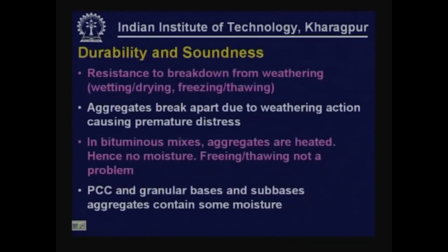Durability or soundness is the resistance to breakdown of the aggregates from weathering, which is the wetting and drying process, and also freezing and thawing. Aggregates break apart due to weathering action, causing premature distress of different types of material layers that we use, bituminous layers and concrete layers.